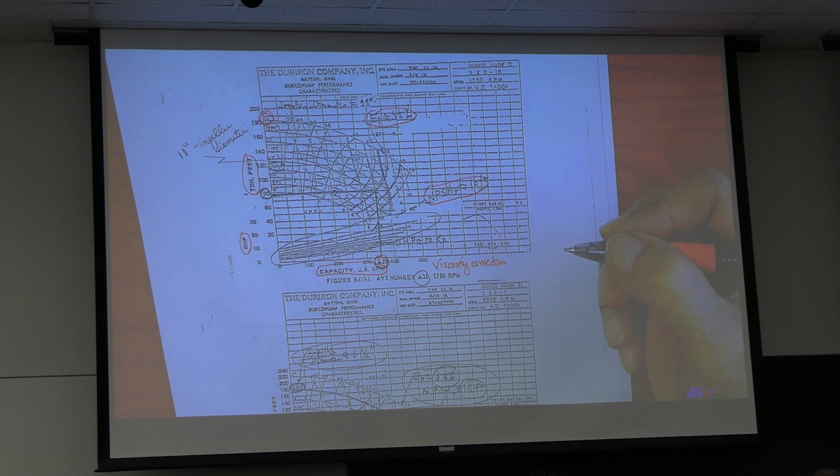Your boss asks you to size a pump. What are the two things you're asking for? Volumetric flow rate and differential head.